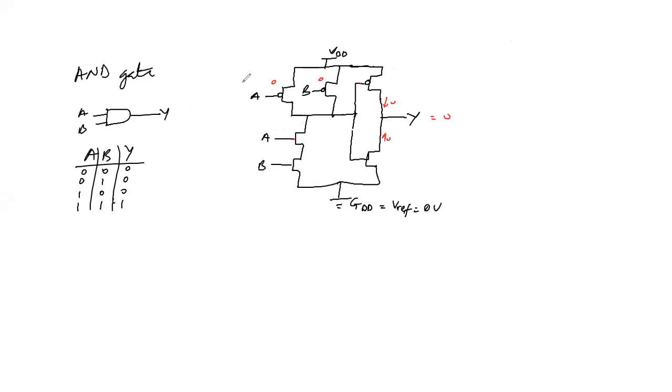Okay. So when this is 0, this is a short circuit, this is an open circuit. And this is a short circuit, this is an open circuit. So since this is open, now a 0 appears here, but now this is a 0, is short, and this is open. So at the end of the day, 1 appears here, and then we have 0. Okay? And now this is 0, this is open here, so what is driving this gate is equal to 0, so the output is 0.